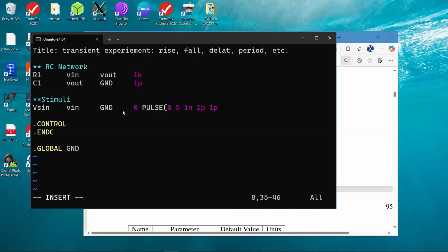Okay. So we are doing 1 K, 1 pico. What's tau? The RC, but what's the number? See, 1 pico is 10 to the power minus 12. That'll be 1 picosecond if you had 1 ohm. This is 1,000 times more. So 1 nanosecond.